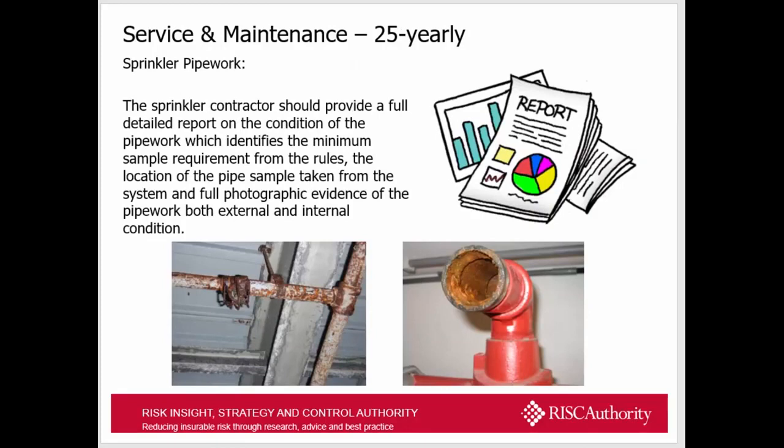Service and maintenance. So we've moved now from 10 yearly to 25 yearly. A recent change of the requirement introduced earlier this year was the inspection of sprinkler pipe work. As can be seen on the two pictures below, we do have issues with regards to corrosion of sprinkler pipe work, and it also depends on the environments that these sprinkler systems are installed in, the condition of the water that's used, and if it's been subject to service and maintenance and adequate flushing.